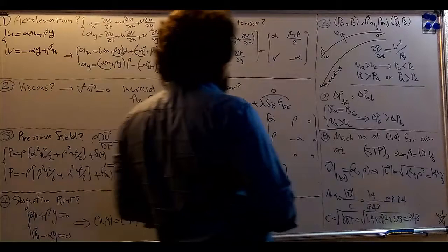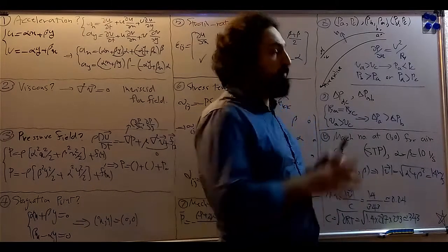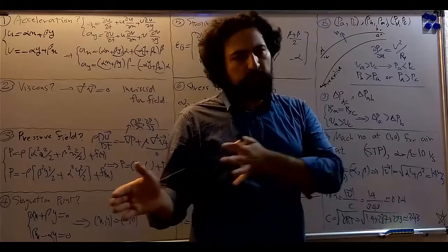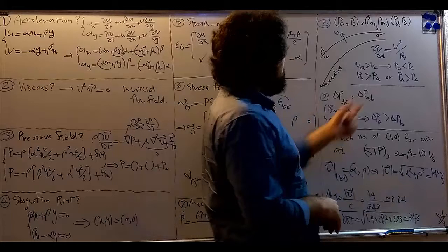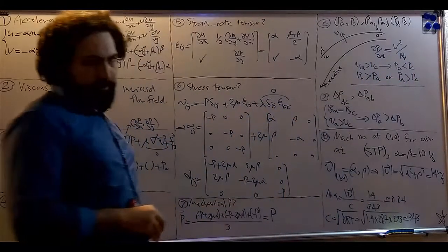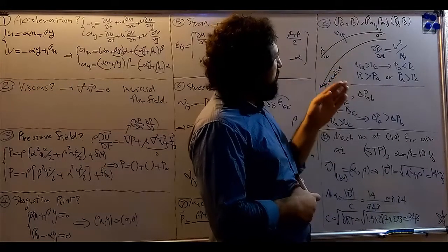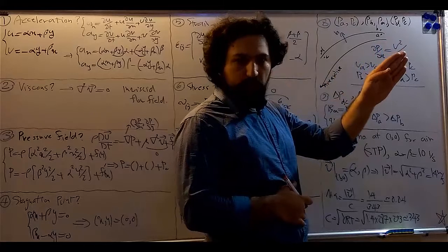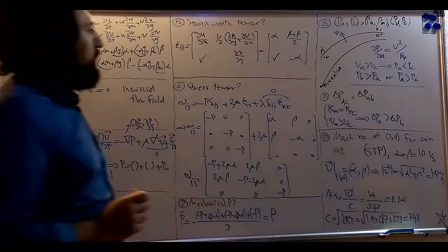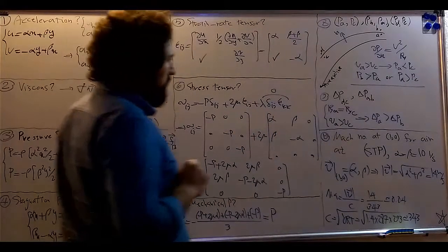Also from the Navier-Stokes equations, by neglecting the body forces and also by neglecting the viscous forces, this relation can be obtained, which is called the Euler equation. This relation shows the variation of the pressure in the normal direction to the streamline, and the other side of the equation is velocity squared over the radius of curvature at that point.